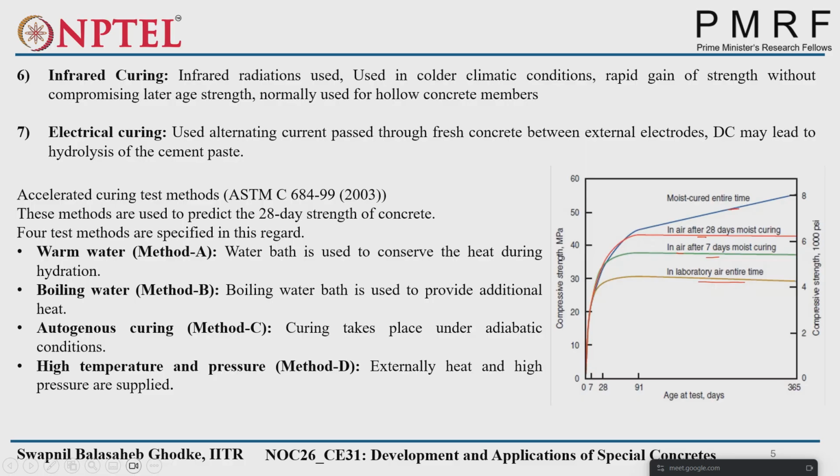But if we go for the continuous curing for the 365 days, you see the strength is continuously increasing, right? So what does it indicate? So later age strength development happens. So that's why curing is more important. Water curing is more important with respect to getting the required strength or required durability aspects or long-term structural dimension stability.